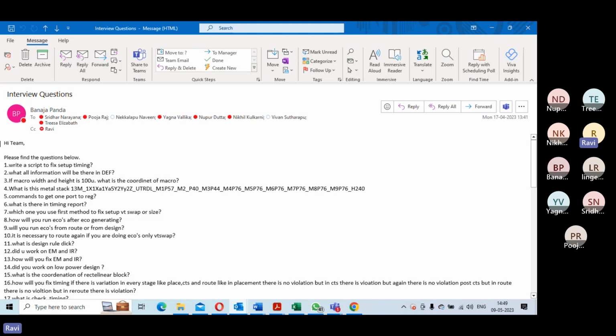So this should be your perspective, and that's why you are touching a clock, so that you will be able to get a common point where you can address more than one violation with a single fix. This is what you have to do. You have to attack the start points before you look at upsizing the cells closer to the endpoints. So you'll have to sort in your script what are the common start points, what are the common endpoints.